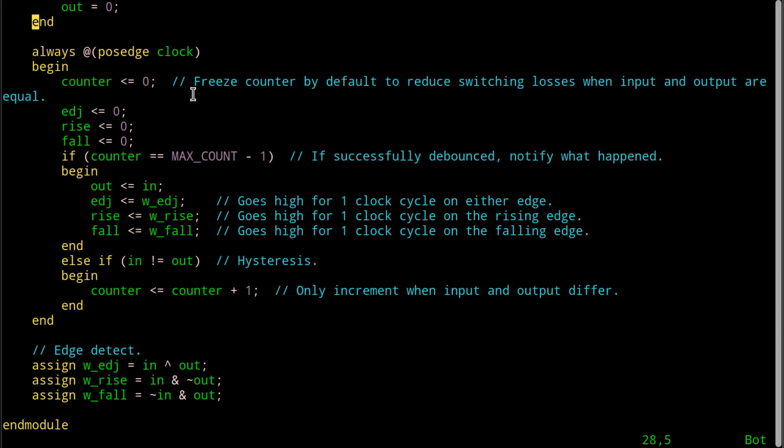Okay, so by the way, simply stopping counters and other logic from changing their states when they are a part of a circuit that's not in use or not necessary to change their states, because the rest of the circuit's doing something else or whatever, is the number one most significant way to reduce power unless you're going to redesign the actual silicon.